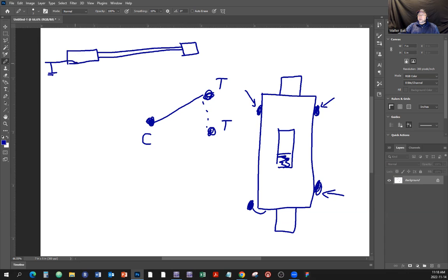It's connected to the bonding terminal right there. Right? Because it's EMT, electrical metallic tubing, it's all metal. So the grounding or the bonding is carried on through the metal to another box, and from that, if it's still EMT, it's going to be carried on to another box and so on. So the only thing you have to do is ground or bond the first box, and then you can carry that through the metallic tubing as the ground.